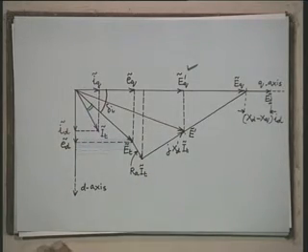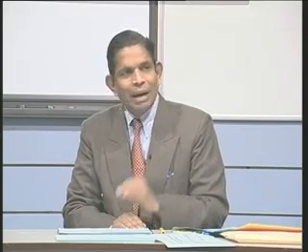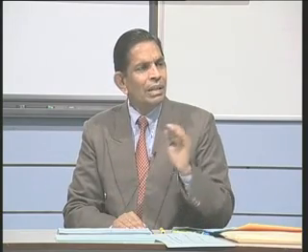Now, let me summarize what we have studied today. We started with the complete model of the synchronous machine. Then we discussed the simplifications. The stator circuit transients are ignored. Another simplification we have considered is that omega r is assumed to be constant. Then the third simplification which we have incorporated is that we have neglected the damper circuits.